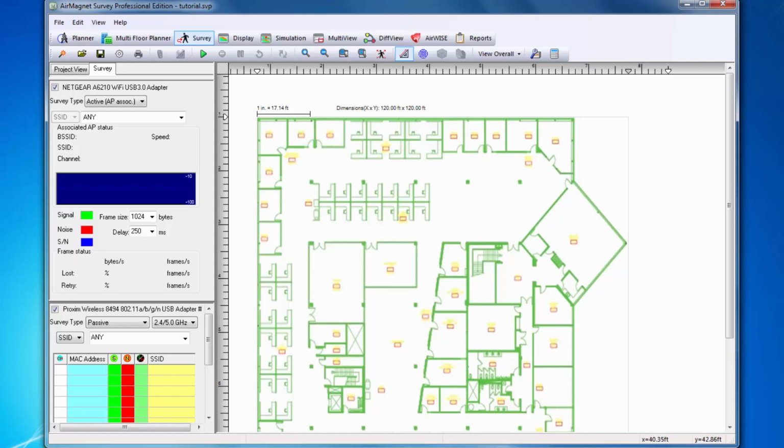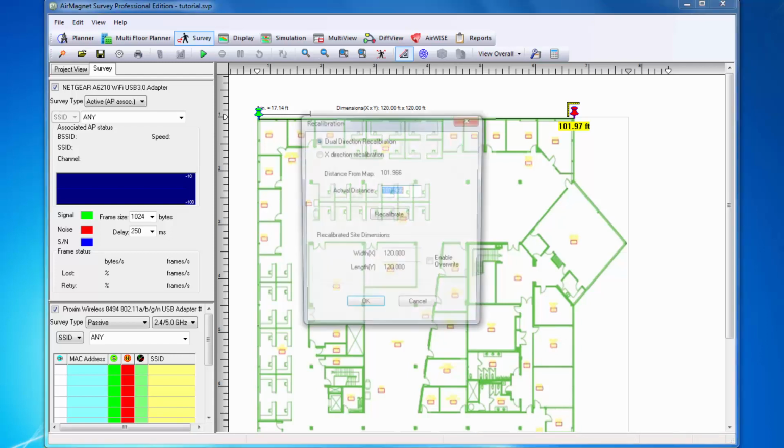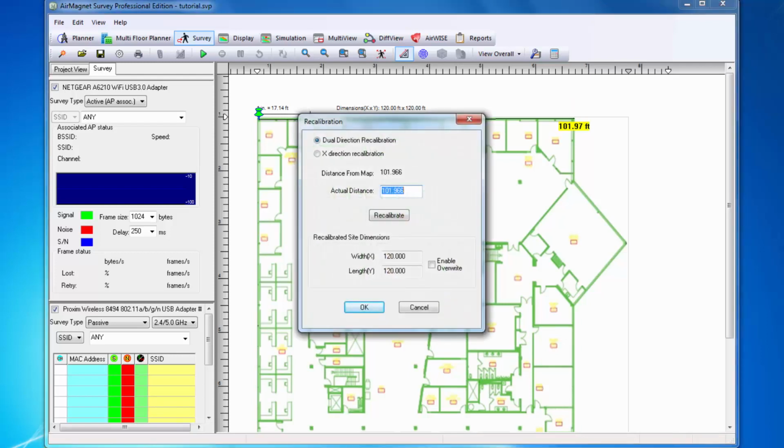After clicking yes, I now have a small pushpin icon for my mouse. I can select 2 points on my floor plan that represent a measurement that I know. I can then state how many feet between those 2 pushpins. In my case, I happen to know that those 2 pushpin marks on my building are 150 feet apart.